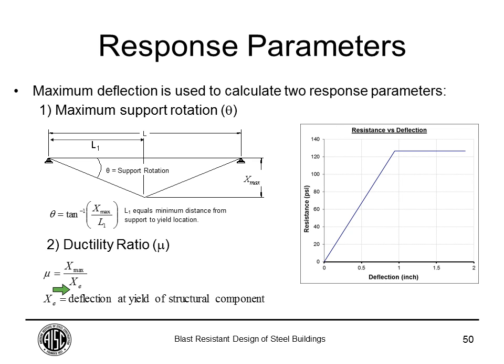Just off the top of my head, you could have a very ductile, very long span that could deflect. A beam that is like double story, going 24 feet, could be deflecting 20 inches and it's still in the elastic range. Well, in that case, you're going to be limited by the support rotation because you don't want anything to deflect that much because it could cause stability problems.